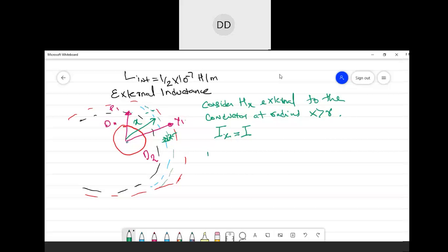so now the flux density at x would become, Bx, as we saw from the previous, is nothing but mu naught Hx, and mu naught is 4 pi into 10 power minus 7. Instead of mu naught Hx, I can write in terms of I, that we derived lastly, that is mu naught I by 2 pi x. This equation we derived when we were calculating the internal flux.